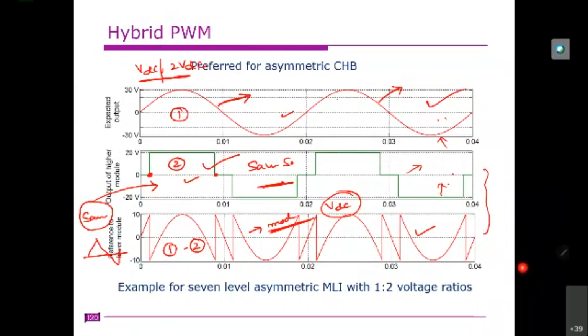So your question is what is the angle of this one, right? Yes, sir. Okay. So you can obtain this in different ways. One, using selective harmonic elimination, you can eliminate certain harmonics. If you want to eliminate the third order harmonic, this angle is 30 degrees, right? So usually this angle is 30 degrees. That means this conduction period is 120 degrees. Clear?